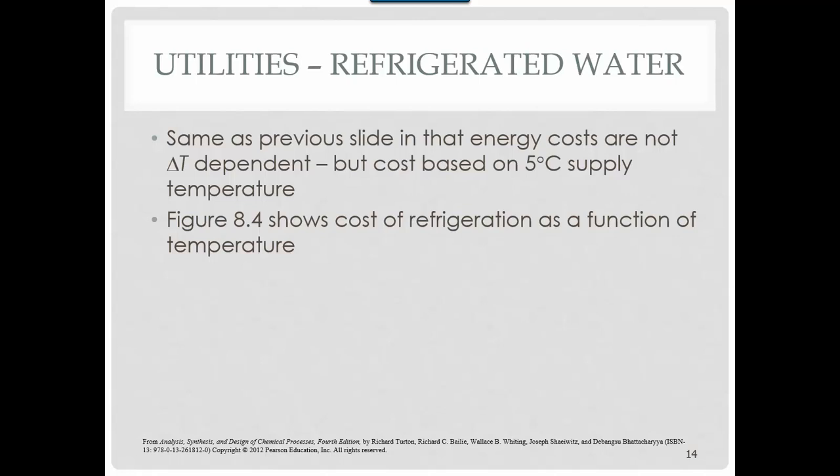Okay? So if you've got refrigerated water, you just need to figure out what the supply temperature is, and that's going to be the big cost. Okay? How cold did I need the water to be when it was going into the cooler? Okay? And that's the cost. It's not how much it comes out at the end.